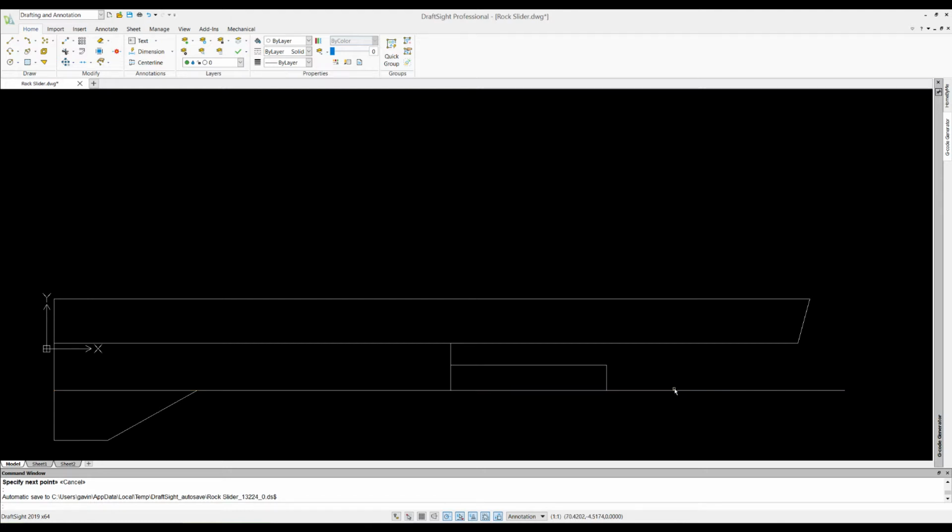So we're going to start. The rest of our part is only going to be 4.5 inches, where this is 5 3/8. So we need to come up the difference of that, 7/8. So we're going to go up 7/8 from here. 8.5. And then that we can just run wild again. Just let it run wild. So there we go. So now we don't need this line down here either. That's our new edge for the rest of the thing.